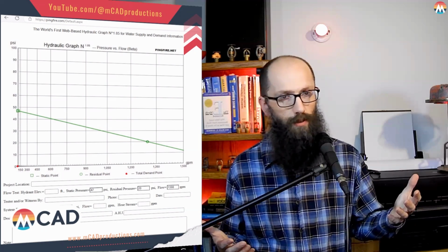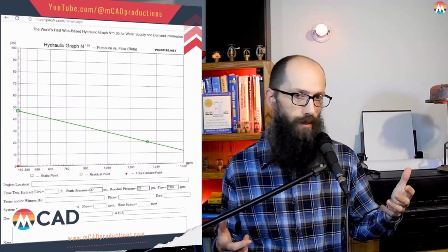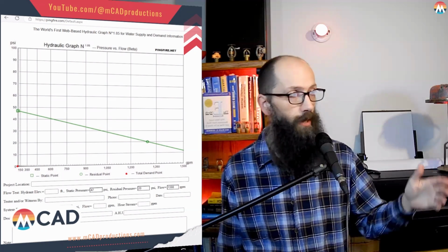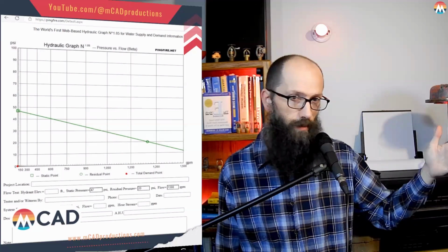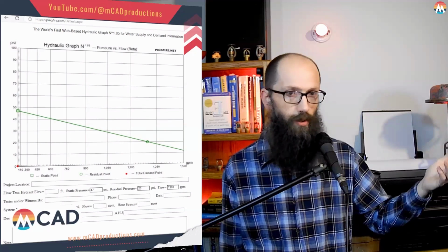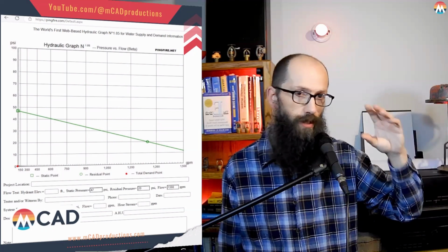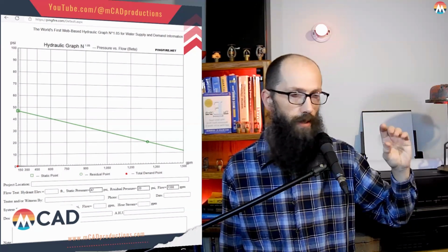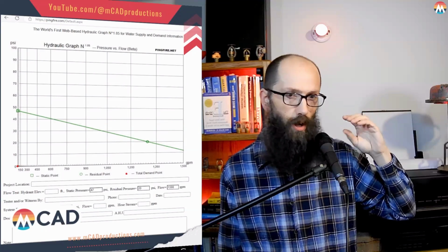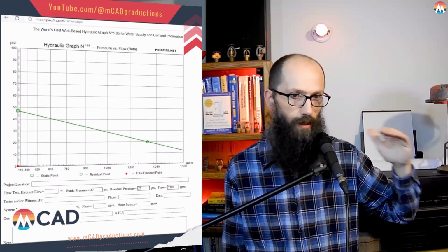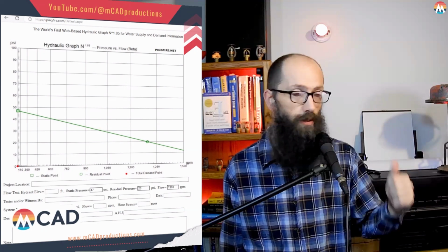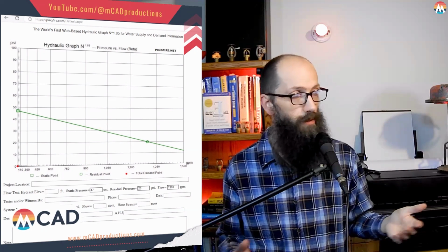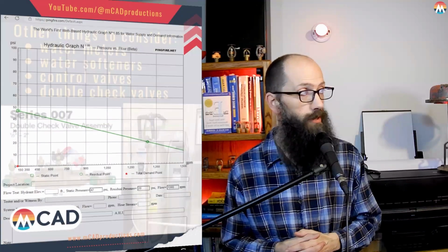When we're designing a sprinkler system, you're going to see a graph similar to this on our hydraulic calc program. This line, which they call a flow curve, which is actually a straight line, represents the available water supply. And as long as the demand of our design always ends up underneath this curve, we will be good. We also have to have a 10% pressure cushion, but the general idea is we need to stay below that line.